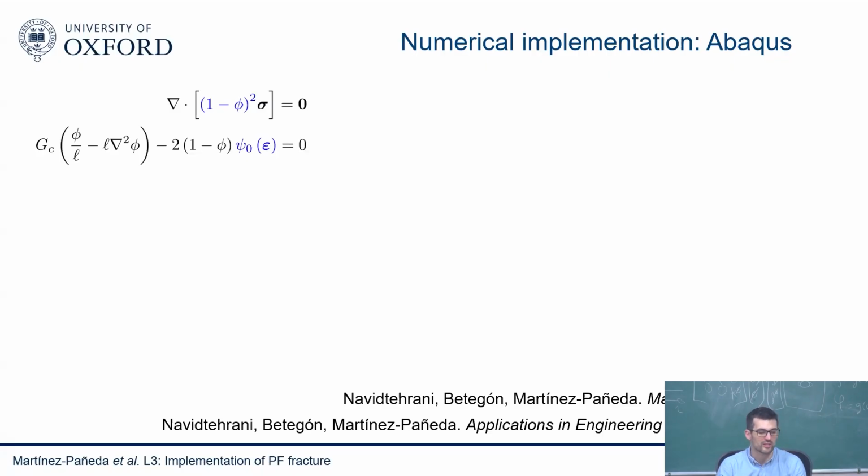And the way to do that is by taking advantage of the thermal analogy, because Abaqus, like almost all commercial finite element packages, I think COMSOL is a bit of an exception in that it can handle many multiphysics problems. But thermomechanical problems is something that all commercial finite element packages can handle. They all have special elements to solve for displacement plus temperature.